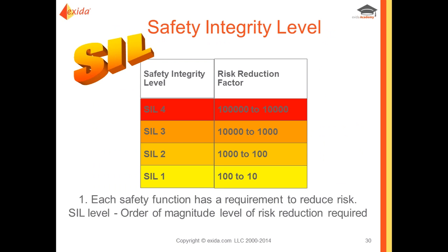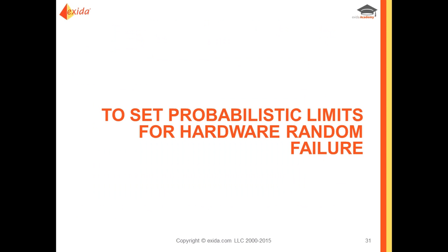To fully understand risk reduction, we're going to look at an example of a calculation. So you have a PHA and it determines that a specific hazard can occur once every 10 years, causing a major release of toxic fumes into the atmosphere. So you're going to want to determine the risk reduction factor for that hazard to occur only once in every 500 years. So it's a simple calculation. Your risk reduction factor would have to be 50.